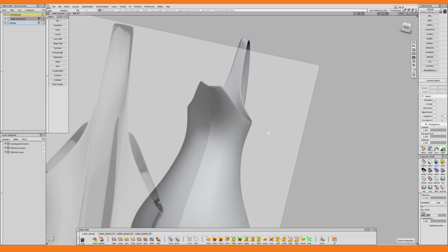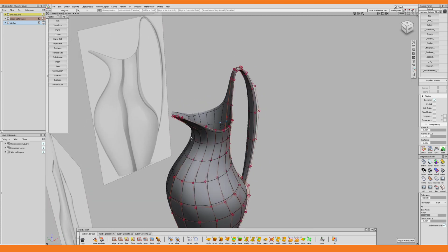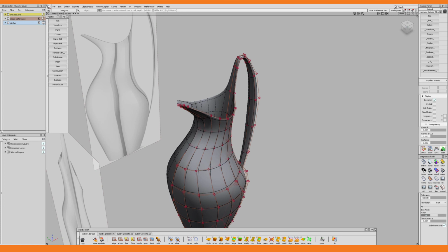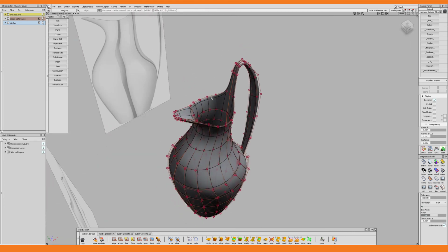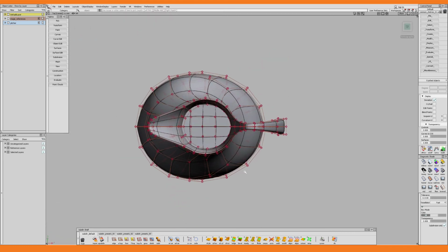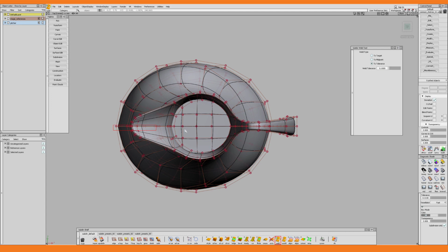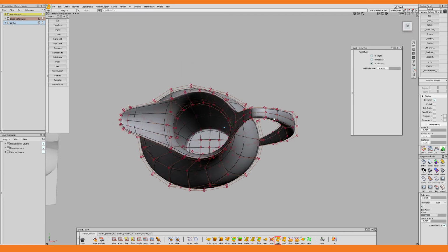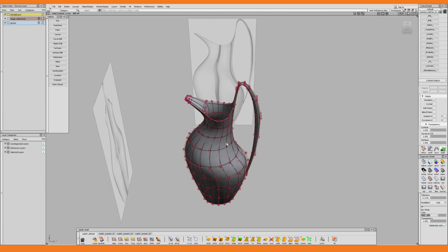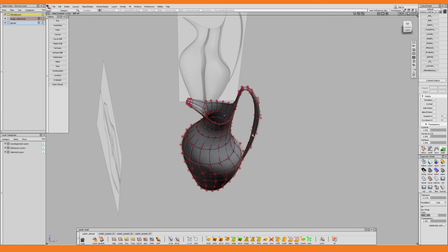Then let's get rid of the seam line. And if you watched any of my other videos, you know that the way to do that is by, first of all, creating geometry from the layer. So go to Layer, Symmetry, and create geometry. Then we want to combine these two objects into one by using the Weld tool. I set it to a small tolerance, and then I drag select across all the vertices of the symmetry plane. And this combines the two pieces into one. For some reason, it also gives me these extra template surfaces, which I get rid of.